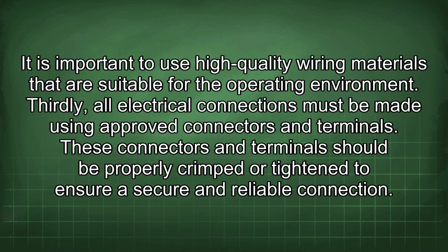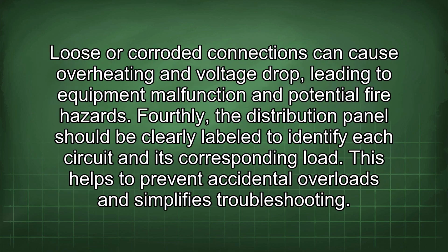Thirdly, all electrical connections must be made using approved connectors and terminals. These connectors and terminals should be properly crimped or tightened to ensure secure and reliable connection. Loose or corroded connections can cause overheating and voltage drop, leading to equipment malfunction and potential fire hazards.